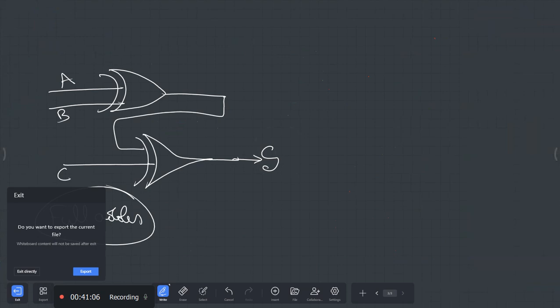Here, whatever sum you are getting, it only depends on the input at that time only. It doesn't depend on input from the previous time. Have you understood this? Hence, this output depends on only inputs at the present time. It is called a combinational circuit.